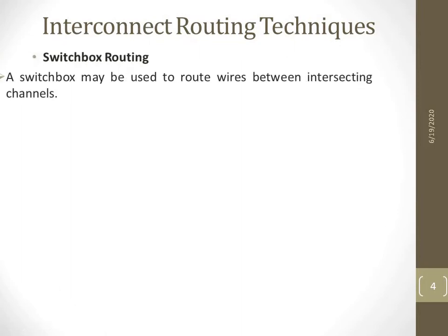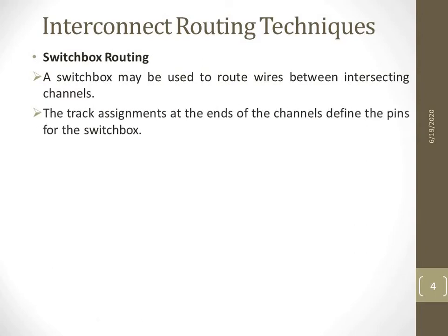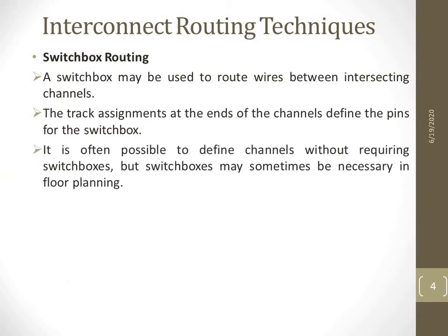Next is the switchbox routing. A switchbox may be used to route wires between intersecting channels. The track assignments at the ends of the channel define the pins of the switchbox. It is often possible to define channels without requiring switchboxes, but switchboxes may sometimes be necessary in floor planning.